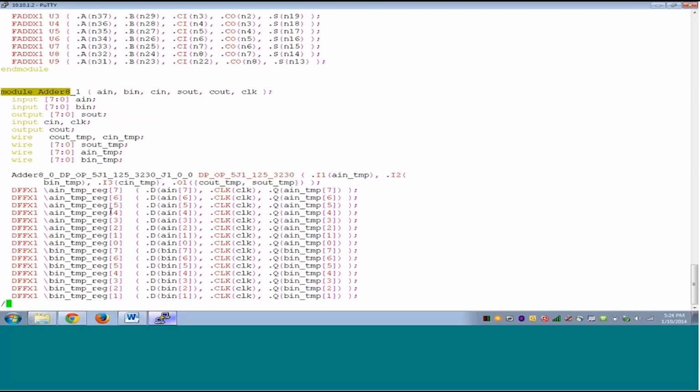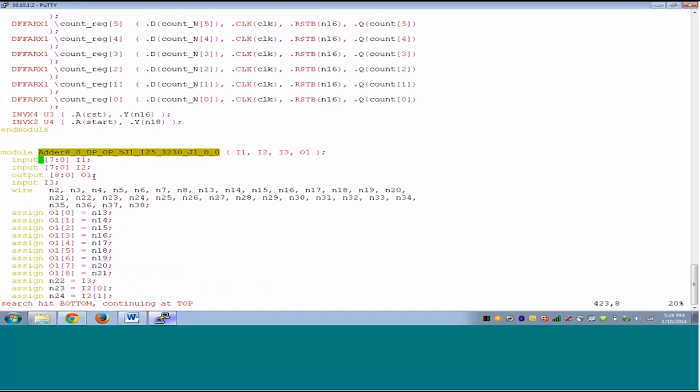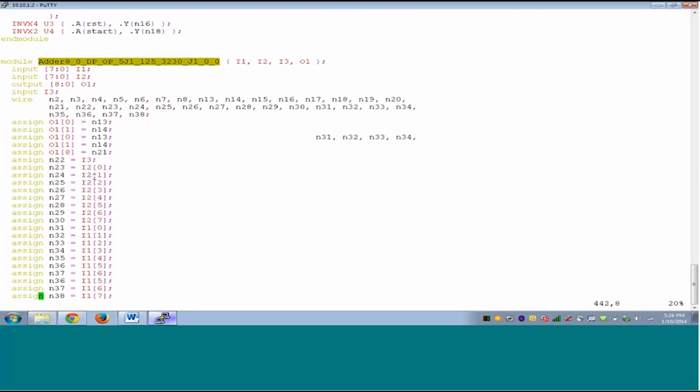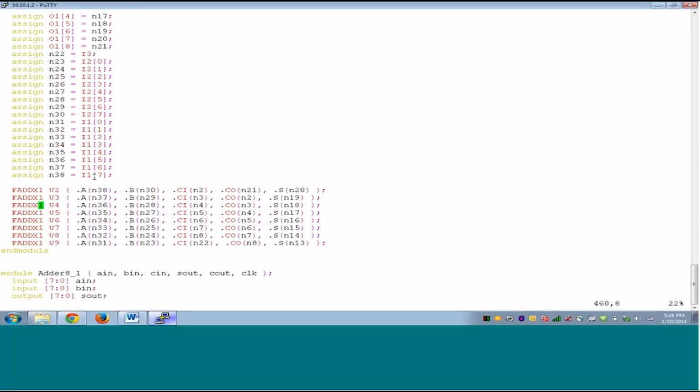Let's look at this module DPOP. Now this is the one that performs addition, right? Again, this is just a combination of full adders, which was expected, right? You add 3 things, 3 bits. It needs a full adder. This is a full adder. Now the number of the full adders, and the way they are connected, will define whether it's area optimized or timing optimized. In this case, we saw from the report resources report that it's area optimized.